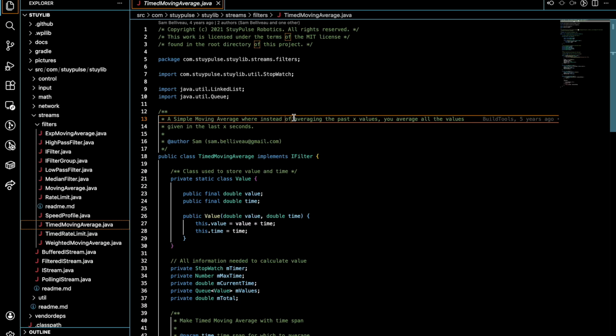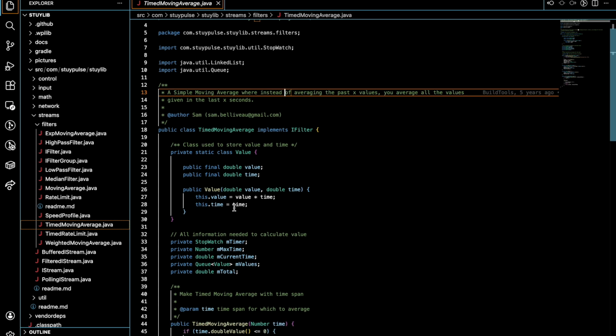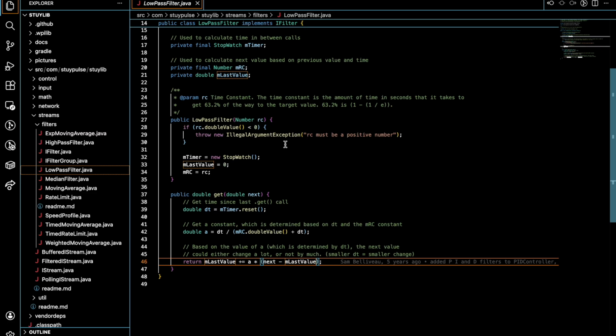There wouldn't be a problem with this if you have quite a small data set. But if you have a PID system, you don't really have the time for that. A simple moving average is analogous to a convolution or a sliding box, and that takes a lot of delay as you're looking at previous values.